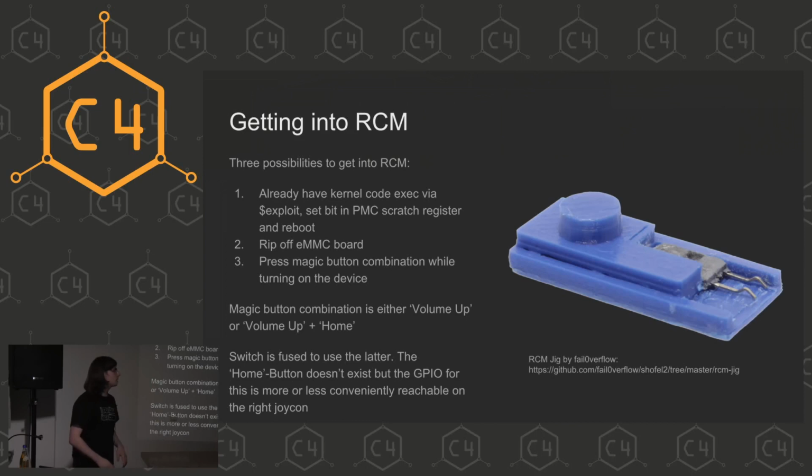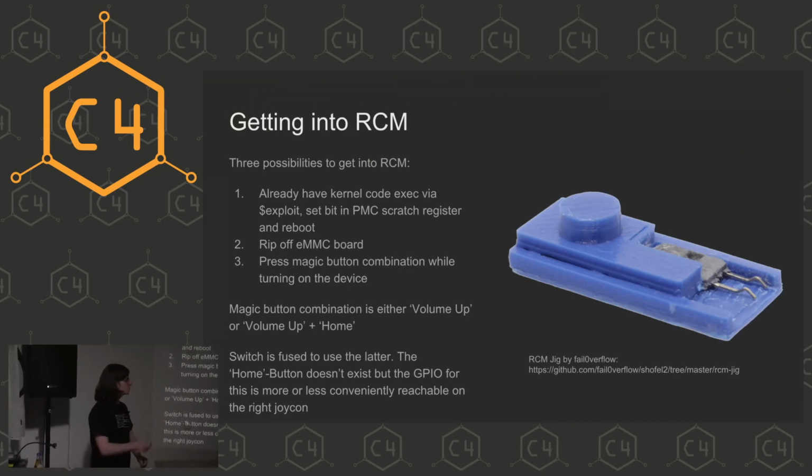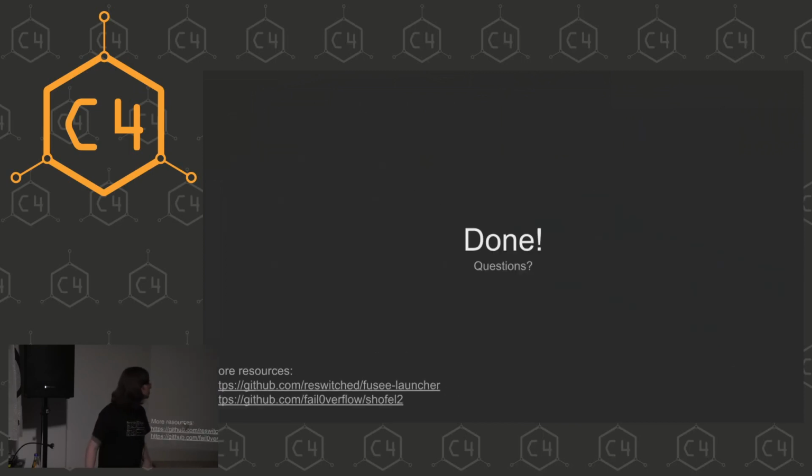I printed one of these and hacked the thing that they glued into there is part of a USB connector. So you can just cut this up, solder the 2 pins together. This is the first and the 4th pin, I think, of a micro USB connector. So you just sacrifice a cable and curse a lot because it's just fiddly. And then you have your own of these jigs. That's it.